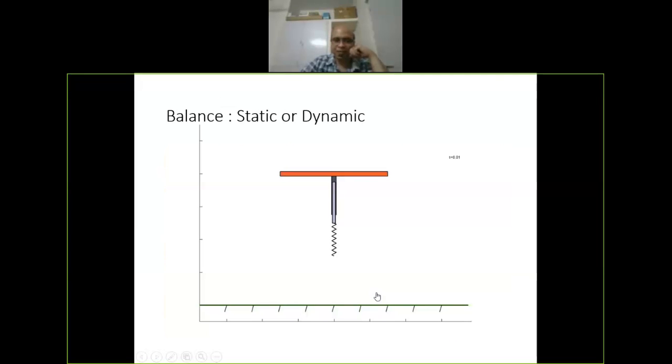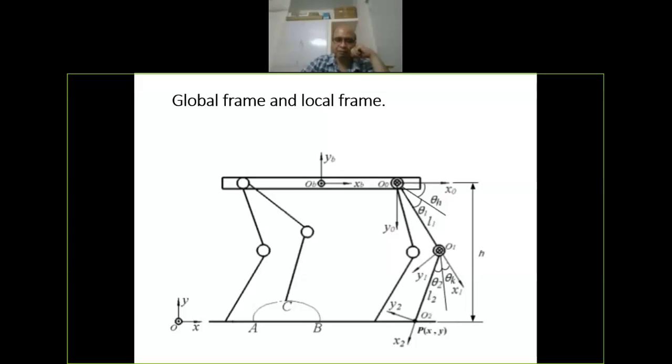So if you're talking about kinematic modeling of this system, then essentially we are seeing that we have 4 legs, and whatever robotics you might have studied or mechanisms you would have studied, we can essentially put an axis frame on the body. My axis frame is 0, which is in the center, and then every leg has got an axis frame which is assigned to it. Okay, and then essentially what we need to figure out is this curve C.